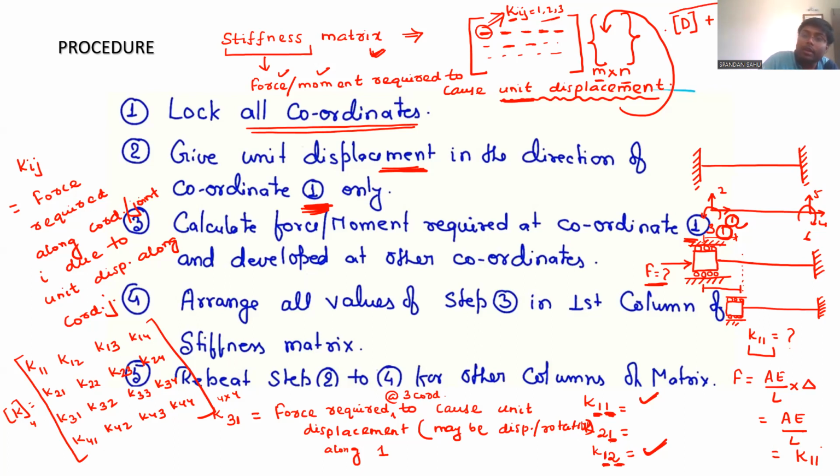In the same way, you can write the stiffness method. And in today's class, we are writing this. We are just substituting it by K, and we will see how this K matrix can be assembled and grouped together to form a global stiffness matrix for a given structure, and how all those unknowns can be determined after forming all those equations in algebraic matrix format, that is, the matrix method of analysis.